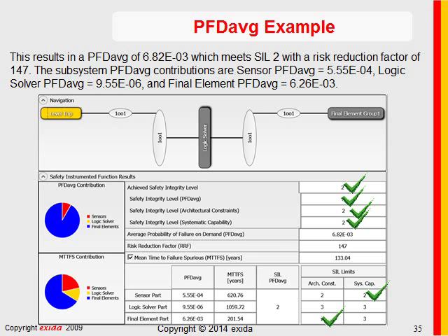All right, well, you can see in this tool the details of the calculation, where the problems are. Interestingly enough, look at this blue area over here in the pie chart. The major contribution to PFDavg is the final element. The tool also calculates a very important variable, your mean time to fail spuriously, and we like to see pretty high numbers.